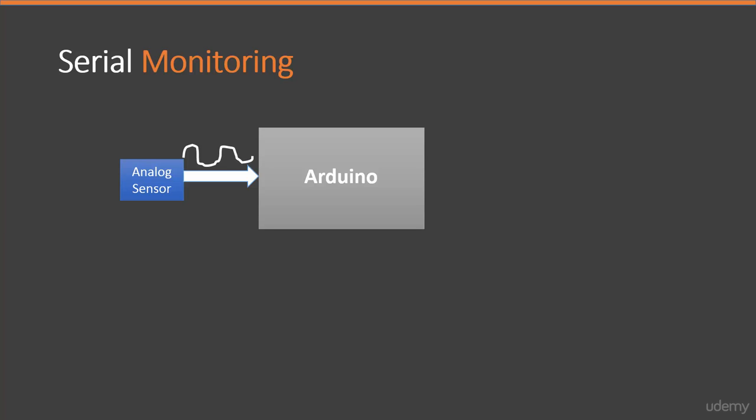We learned that the Arduino will convert the 0 to 5 volt analog signal to a digital number between 0 and 1023. However, sometimes that is not the case, meaning we will get a different subset range within the maximum values of 0 to 1023. We will get something less than that. The main reason for this is that every sensor is a little bit different and will provide a varying range of voltage levels depending on what it is actually sensing.